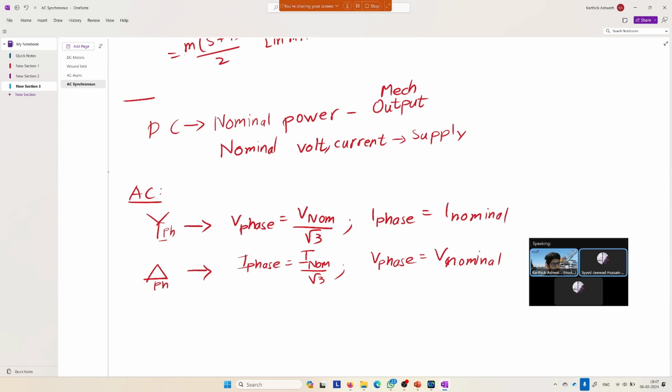As the motor, especially in DC, spins faster and faster, the rotation itself creates a back EMF in the circuit, which decreases the amount of torque that can be made. That's what I usually talk about, right? You have the armature resistance, and then this is the VB or U induced back EMF.